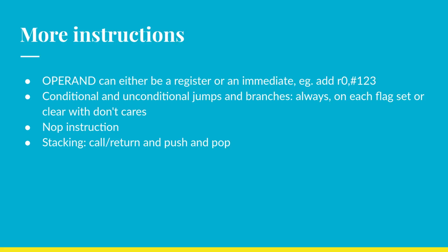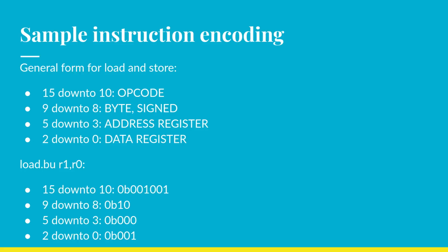In terms of the stack pointers, with the push and pop instruction, that's set in the instruction code. So you would have push, the destination stack pointer, and the source register that you want to push. With call and return, that's also the case where the register to use is encoded in the instruction, but the assembler hard codes it for R7 out of convention, just because I don't want to set the stack pointer every time I call a subroutine. It's not particularly useful.